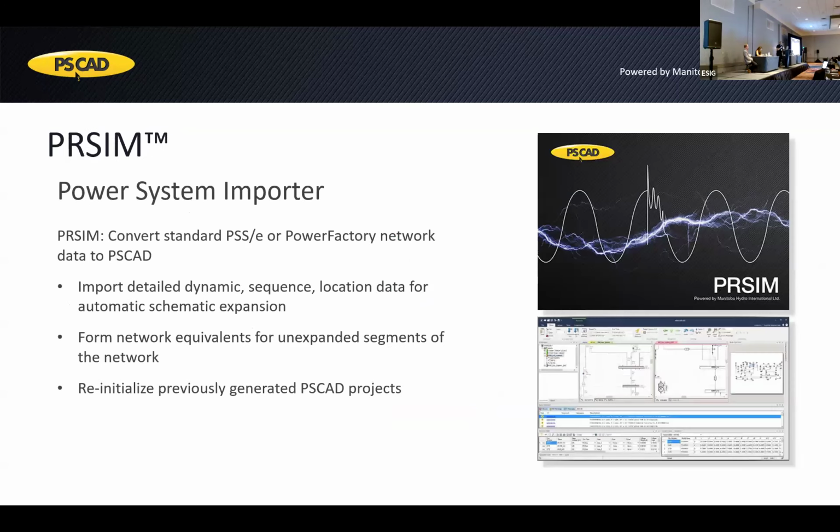But what about the wide area networks that we're starting to look at? For that, MHI has developed a tool called PRSIM, and it's our power systems importer. So what this does is it takes a large network database and does the necessary pre-processing to make a case usable in PSCAD. So currently, PRSIM can convert PSSE networks and PowerFactory networks.